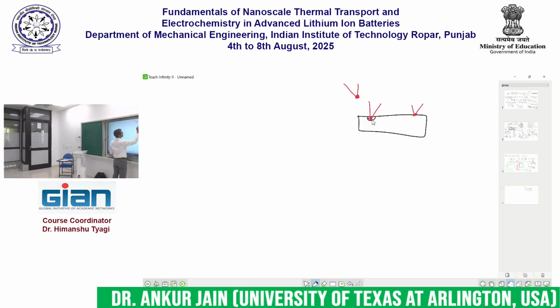You will probably put a lot of thermal paste around it and so on. Is that possible here in our measurement? No, I can't drill a hole in my cell, right? So that's out of the question. But nevertheless, I will want to put a good deal of thermal paste all around my thermocouple in order to make a good intimate thermal contact with the surface of interest.